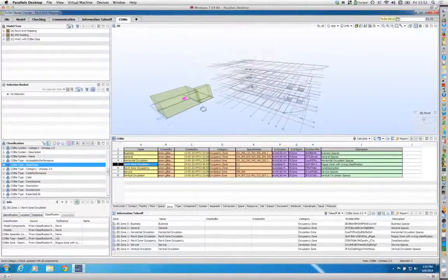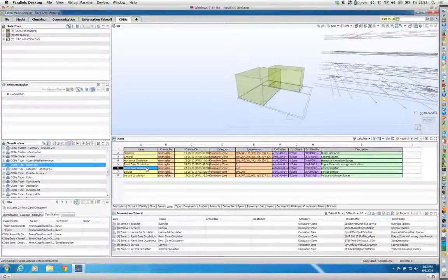So I haven't had to manually import this data. It's actually done the zones correctly as true IFC zones if you use that zone name field. Again, some of the documentation for that can be found on the download for the IFC exporter, which you can get, the free exporters for Revit. They tell you there's certain functionality that you can apply at each level of those. So check the